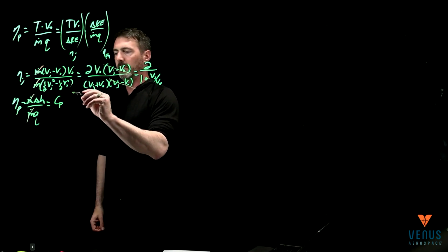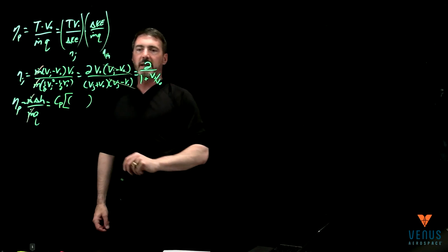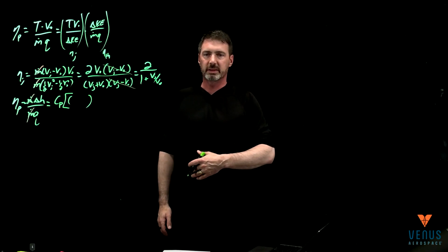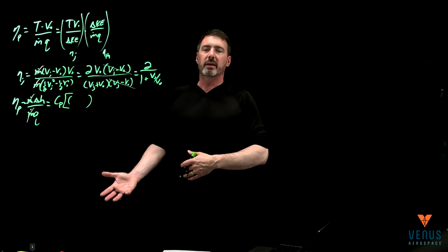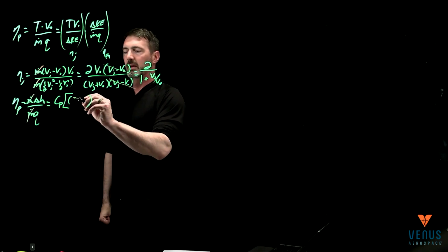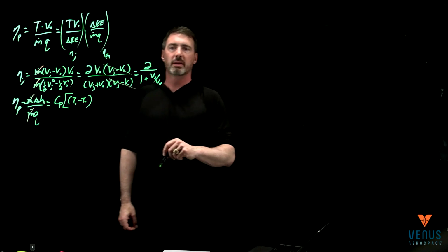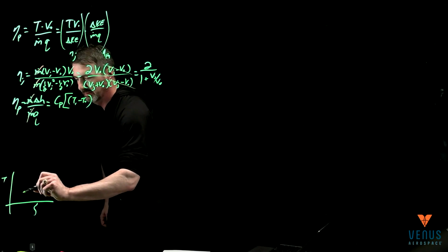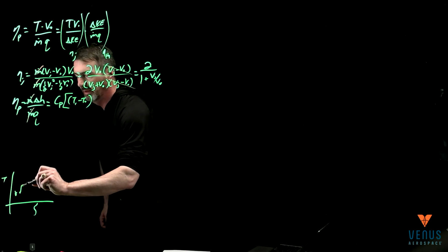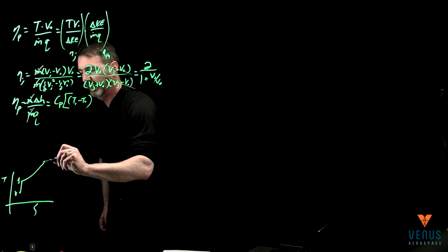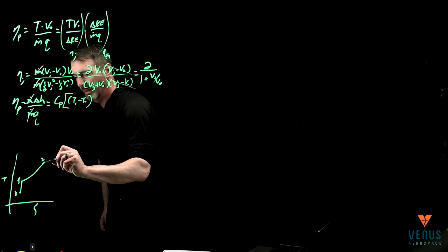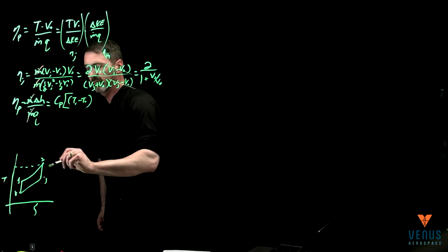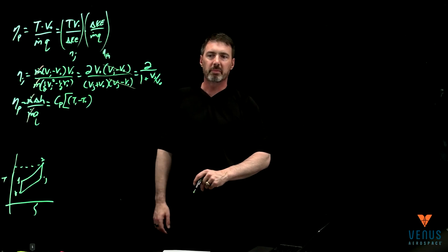There is what it takes to compress it. Even though there's not a pump, you are using the forward velocity to compress it, so this would be the power taken to compress, T1 minus T0. Maybe I'll try down here the T-s diagram of states. We're starting at 0, compressing up to 1, heat adding up to 2, and then expanding to the jet. And remember I said that our material maximum would be there.